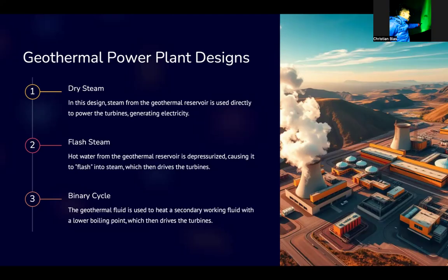Most geothermal resources produce not the dry steam but a pressurized two-phase mixture of steam and water, predominantly water. So the majority of the geothermal power plants currently operating are at liquid-dominated resources, which use a flash system or the flash steam energy conversion process. When you say flash steam, we have a flash vessel, which is often used in the flash steam to improve the plant efficiency. It separates the steam and the water in that flash.